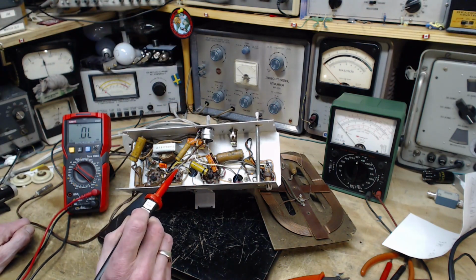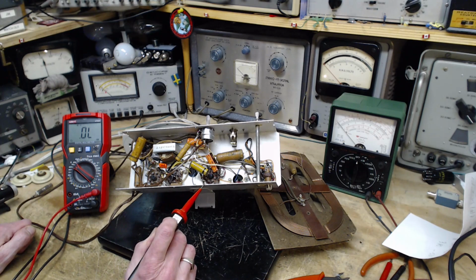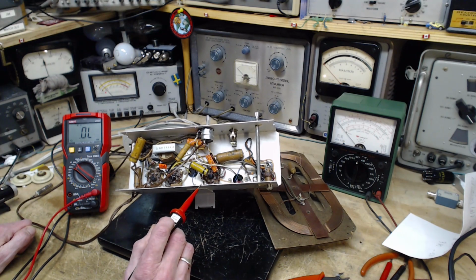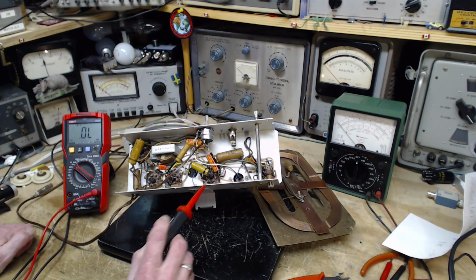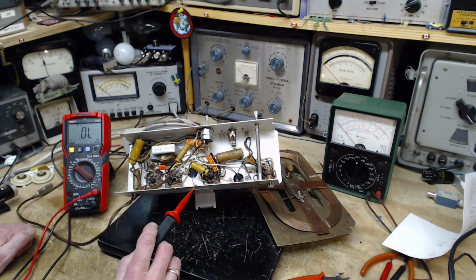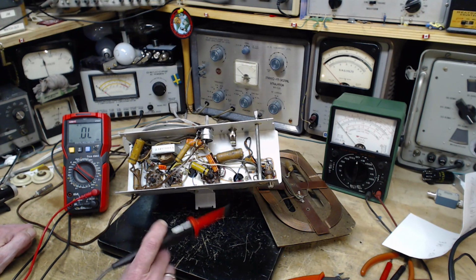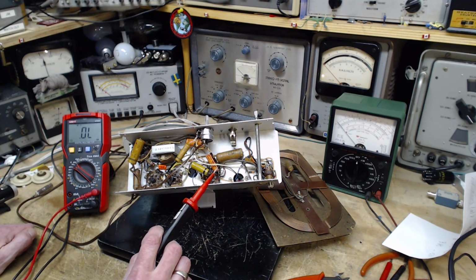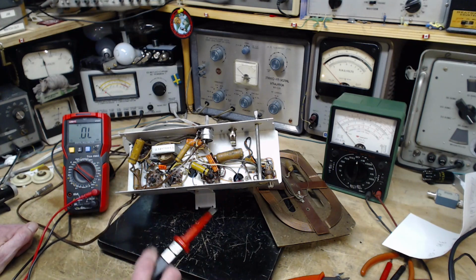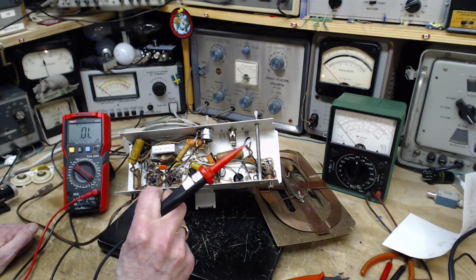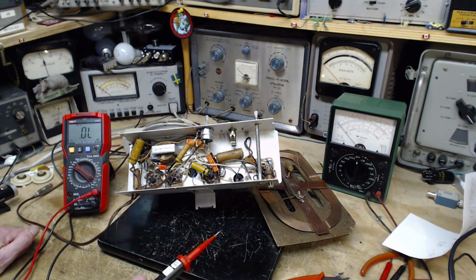We'll check the button again just in case somehow what I did fixed it. Button does nothing at all. The actual amount of current we're reading now, without the capacitor and without the resistor, is 175 microamps. So somehow 175 microamps makes it from the circuit into this chassis under this test, when there's a resistor here. If the resistor wasn't here, this meter would probably go a lot higher.